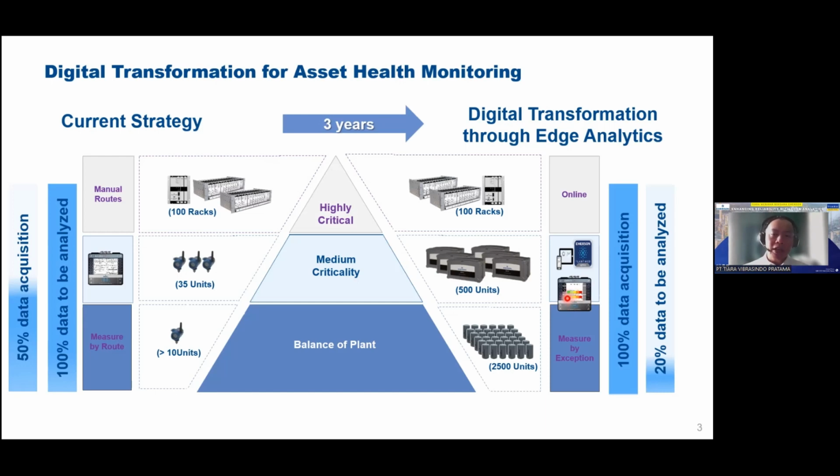So not to say that you do not need your routine data collection or your portable anymore. Portable is still very powerful for further investigation, because currently I'd say portable still gives the best data, in terms of the data richness and so on. You still get a lot more from a portable analyzer. So what it does is automatic monitoring here will give you an alarm, will tell you, oh, look at this machine, there's something happening here. Then you can go out to those machines and do your diagnostics. So that is what it means here now.